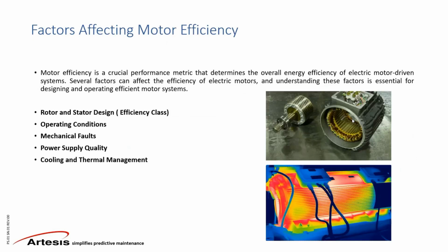And the second thing is the operating conditions. What are the operating conditions of the motor? One factor is the load, of course. What is the size, if the motor is the proper size or not, and if you're running the motor under low operating conditions or low load levels, then the motor will become inefficient. Other factors such as the conditions that the motor runs in or the contamination, as well as the cooling, will play, again, a key factor in the efficiency or the performance of the motor.